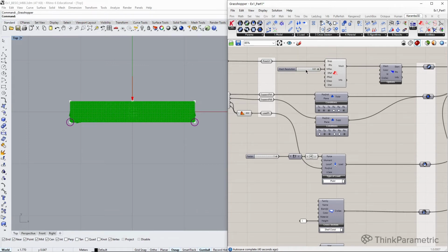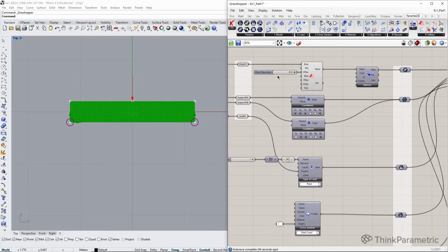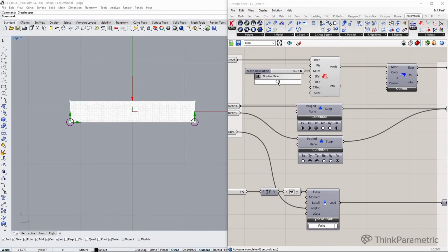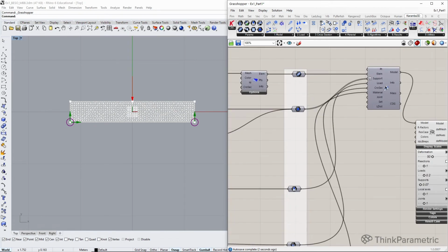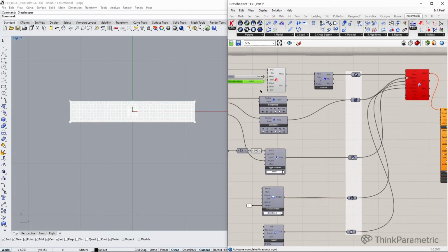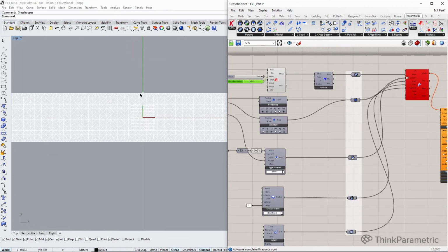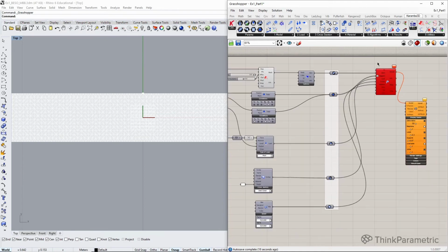And in case of this high resolution, it works pretty well. We have no bug here. But if I change my resolution to, let's say, 5 centimeters, 5 centimeters actually works, and if we go to 4, it also works. So it depends on how we subdivide our mesh. We could have this error, and you see that it cannot find the point load.